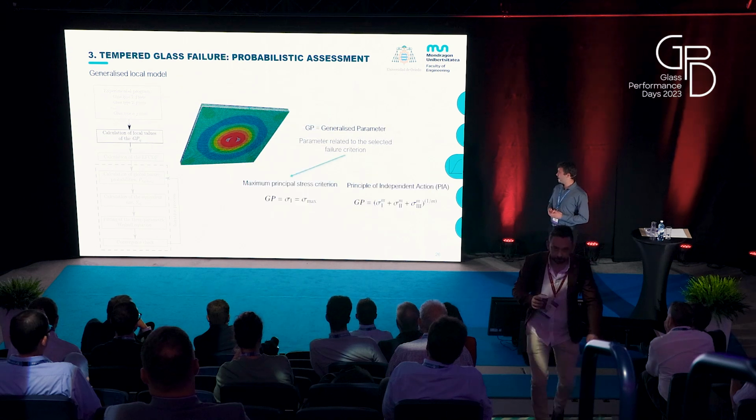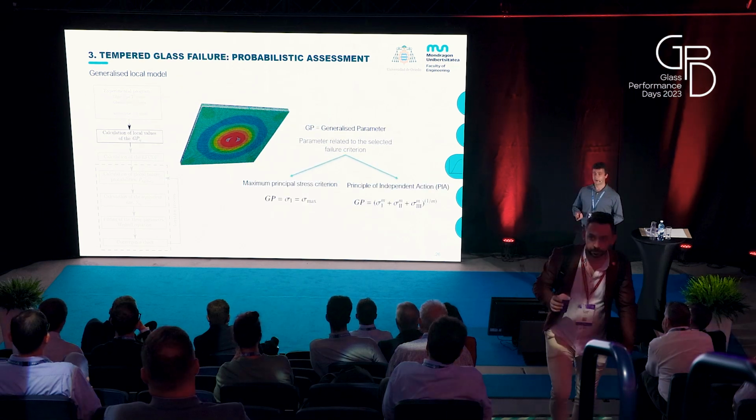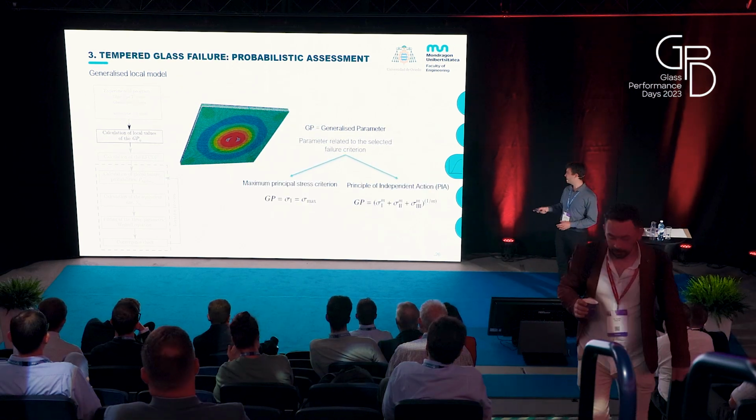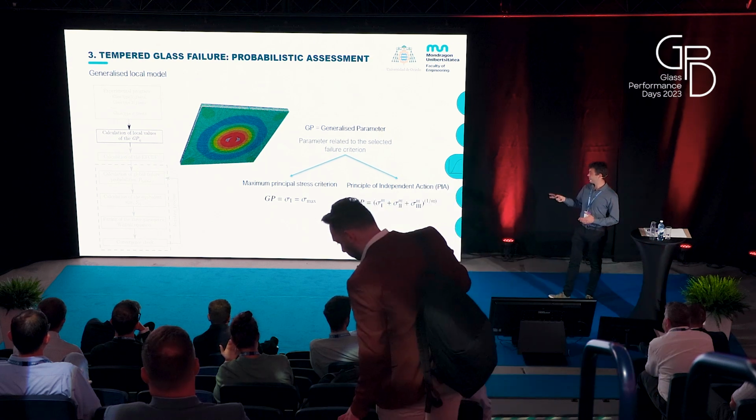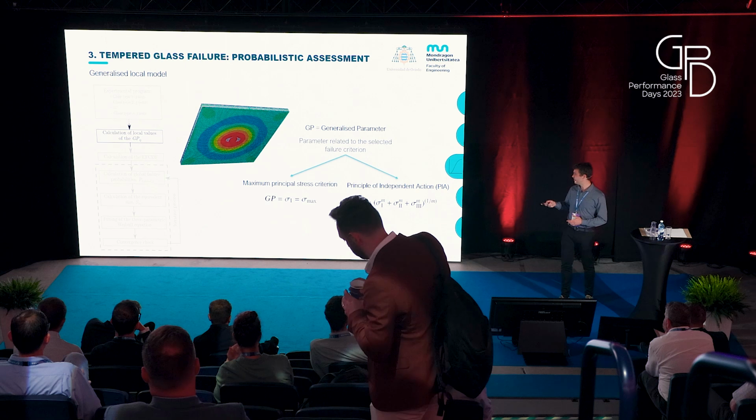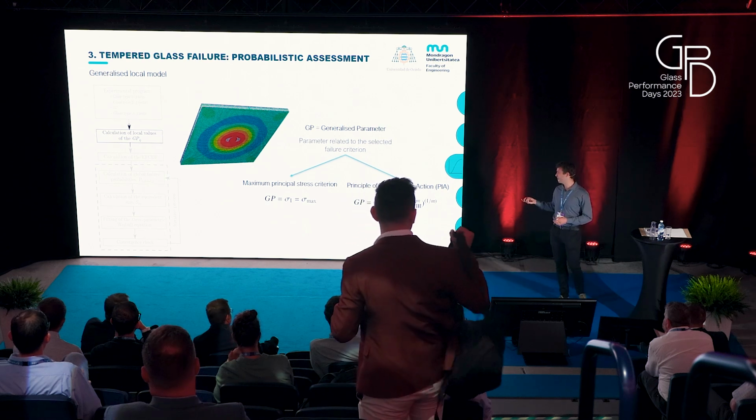Then we calculated the distribution of the generalized parameter. This parameter is related to the selected failure criterion. And in this work, we analyzed two failure criteria, the maximum principal stress criterion and the principle of independent action.